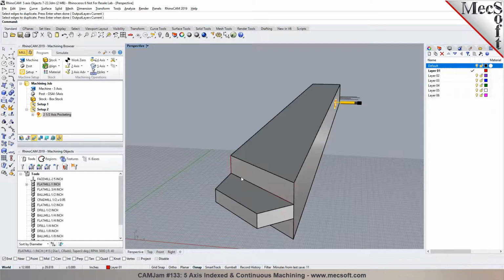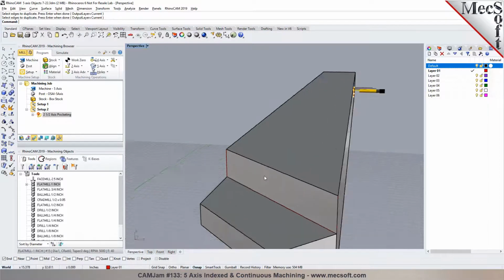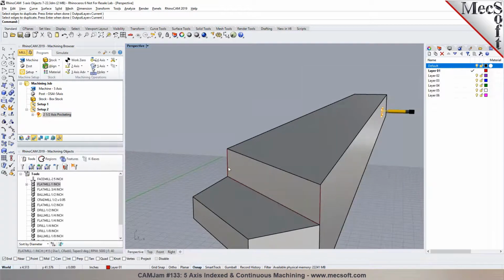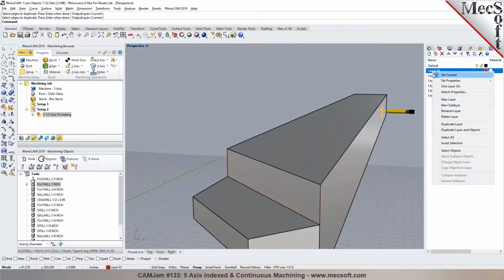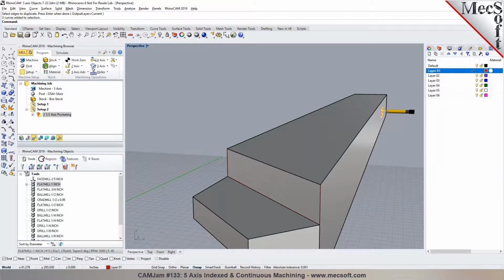And I want the cutter to come in at this angle to cut this out, and I can compensate based on the thickness of the cutter, what I have here. I can basically select these objects in here, and I can also move it out by however far based on the thickness of the blade, so we can do an engraving operation for it. And also, I'm going to check the direction in here of the curve. So you want it to start cutting from this direction, following this, and then retracting, or you can flip the direction in here, going from this direction in here.